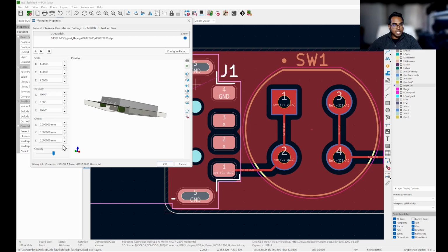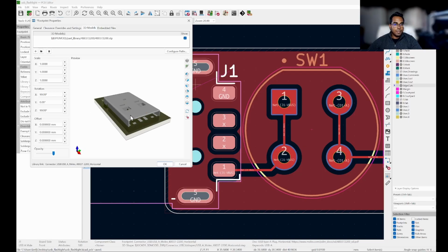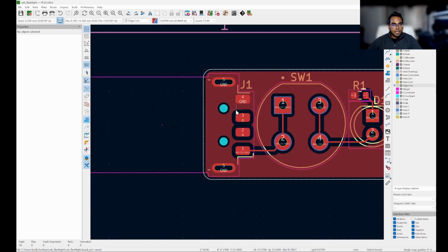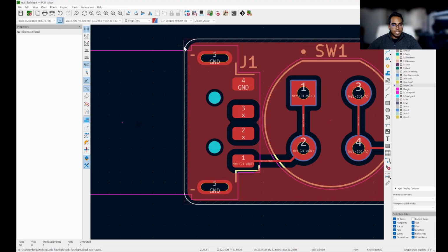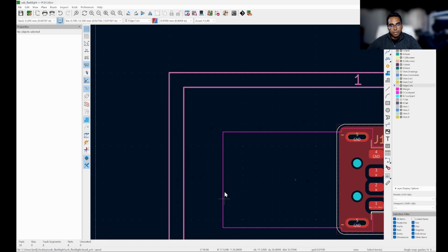To do that, you'll go down to your Z offset in the actual offsets category, and it looks like we can just shift it up by, oh wait, never mind. There is no actual PCB past this line right down here. So the connector is actually supposed to be inset partway and sort of level with our board. That's why, well, I'll show you in a second. If we click on OK and save this, that's why we cut off the PCB way up here, even though the USB connector itself extends all the way out to the edge of this purple courtyard line over here.